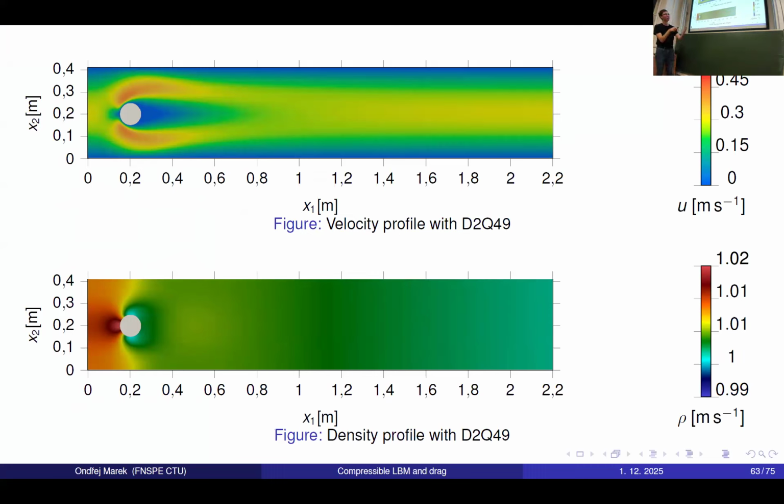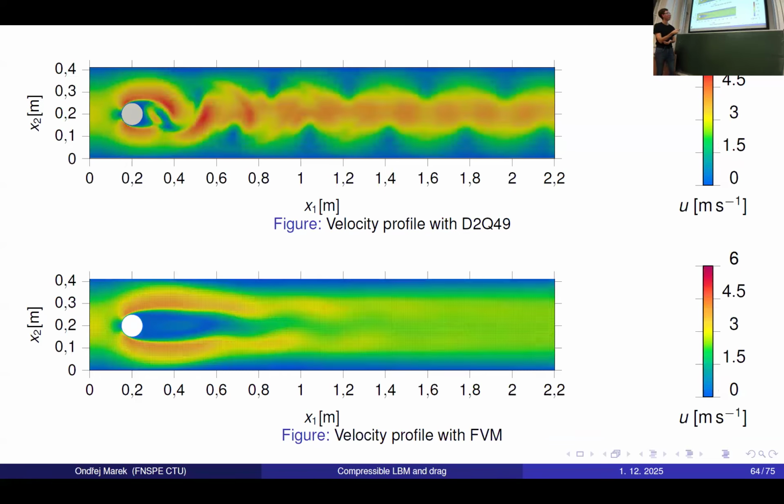The difference is its density, but linear, just a linear scale pressure in Lattice Boltzmann method. So the difference is just 2% in this case. We can see that higher pressure, higher microscopic density is at the object, in front of the object, and then we can see that throughout the whole domain, the pressure, the density linearly decreases, both from the inflow condition that the pressure gradient should be equal to some value.